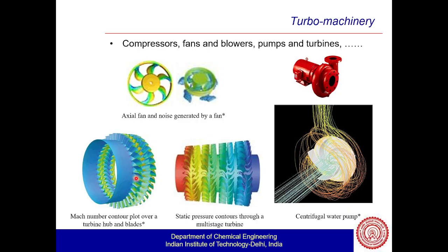And which is going to increase the lifespan of the turbine you are using, because as we know, if we use a poor material which is not sustainable at that impact velocity, then it may break down, and fracture may happen and propagate with time, which will reduce the lifetime of the equipment and may result in sudden failure. So those things are pretty much important.